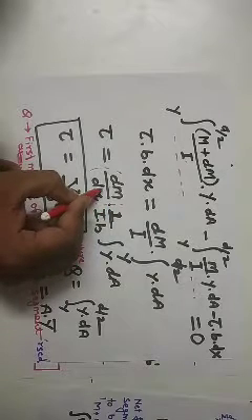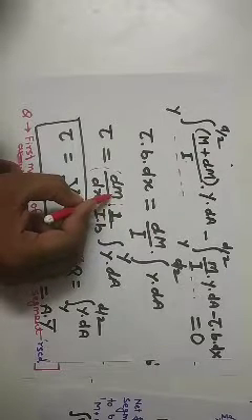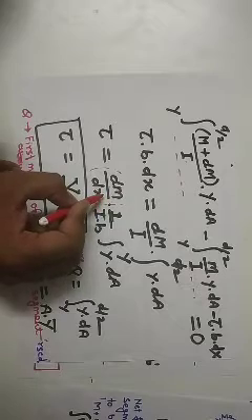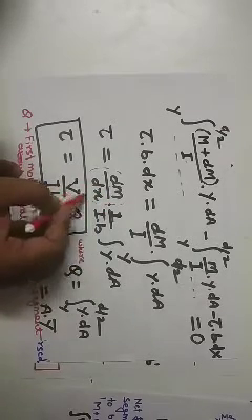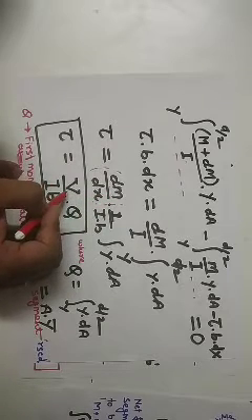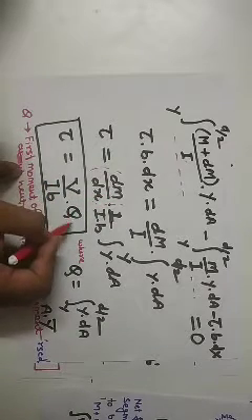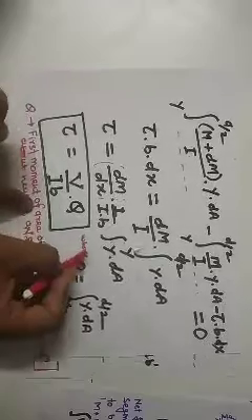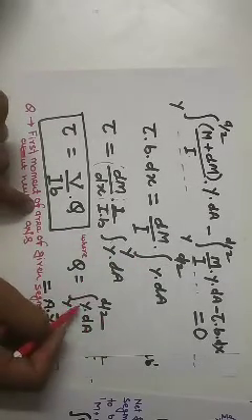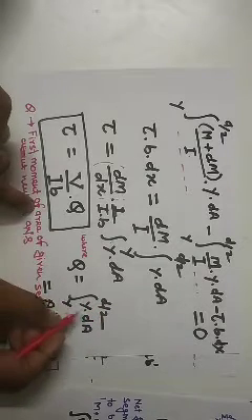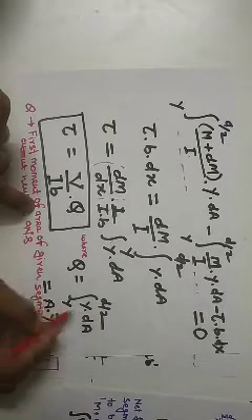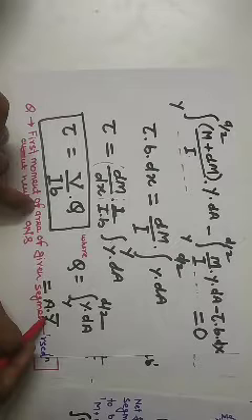And this dM/dx is the shear force, because we know that the rate of change of bending moment with the length of the beam is known as shear force. So this is V/(Ib) times Q, where Q is the integral of y dA, and in this case dA varies from y to d/2. And we know that this is equal to A times y bar, right?